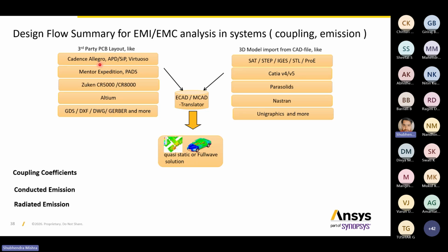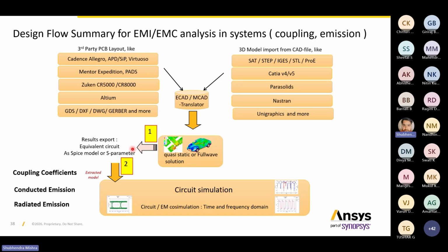Cadence Allegro, LTM, Zuken or any tool, you can import the model here in different formats like ODB++, STEP file, STL file, anything you want to import. When you're talking about the ECAD models, you can import like for like the ODB++, EDB format, ANF, Gerber, anything you want to import, you can import it here. And then we move to the full wave simulations and evaluate the S parameters. And after S parameter, we will move to the circuit simulations.